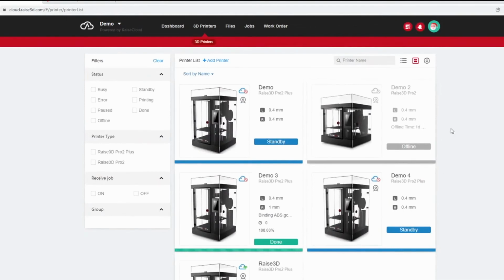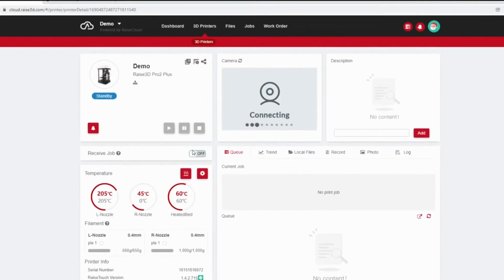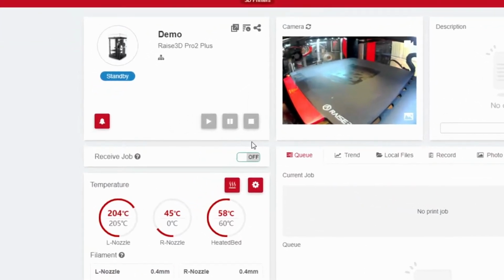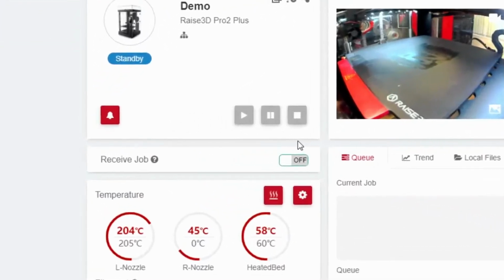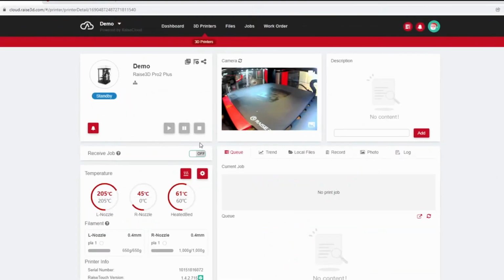And then if I am going to, for example, start a print job, it'll change that state to receive job. So whenever a part finishes, it does completely lock the touchscreen and wait for a user to confirm that it is ready to accept the next task, and that it should go ahead and just pull that next one. We just don't want there to be any risk of it running a new job before our current job has been removed. So that's why there's that.